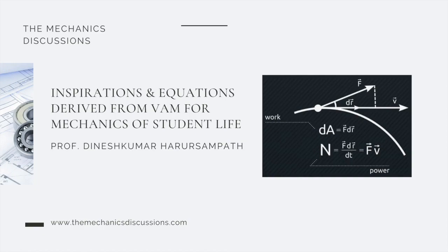For example, in the case of helicopters, where you're looking at cabin noise, how it is getting affected by the noise generated from the rotor, how you isolate that, the isolation systems and things like that. In designing some of these, much better decisions can be made once you understand this from a variational perspective, because a lot of the trial and error method will go away and you'll have much better informed decisions on how to redesign the isolation system, for example, in order to reduce the cabin noise coming from the main rotors.